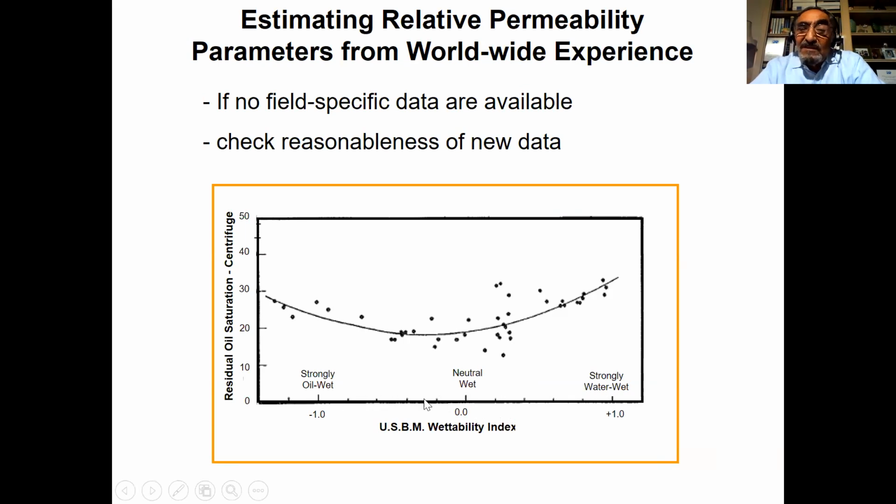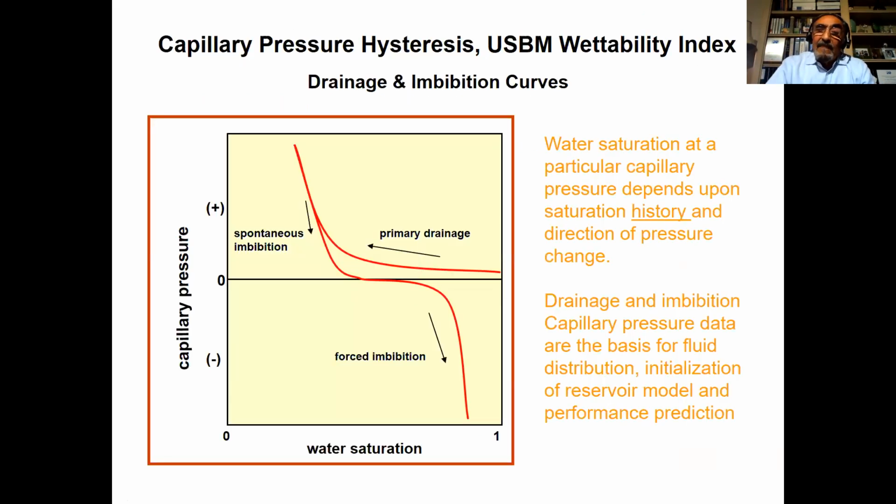The problem is the majority of the reservoirs are in the middle in here, around minus 0.1, 0.2 to plus 1.12. Again, it does not represent a true picture of the variability at the pore level or core level. Now, this is the technique that I just mentioned. You measure capillary pressure using the centrifuge method, primary drainage or secondary drainage, and then imbibition, and the area under the primary or secondary drainage and the area under the primary imbibition, you get the ratio, and that represents the variability.